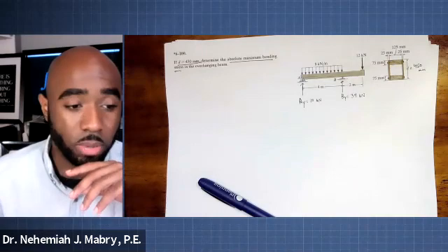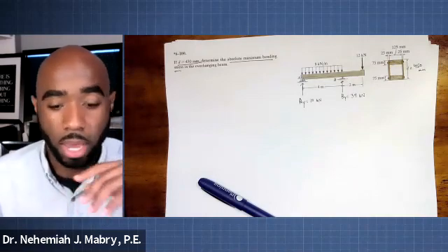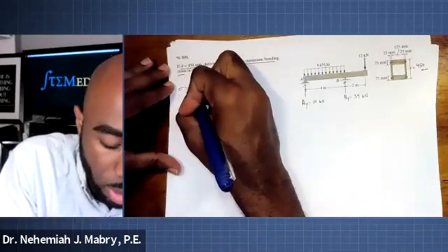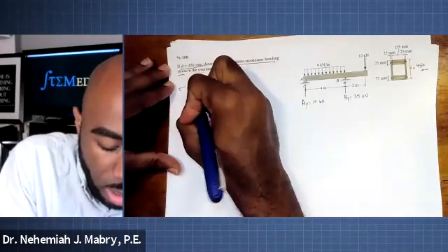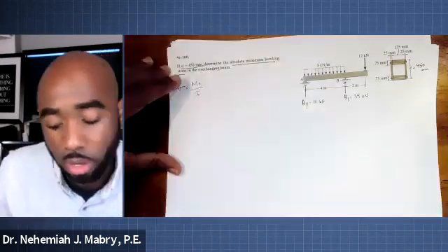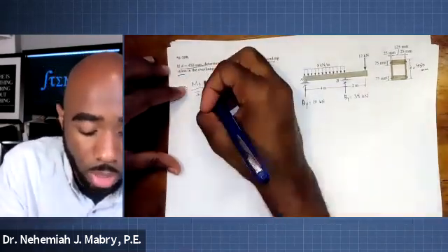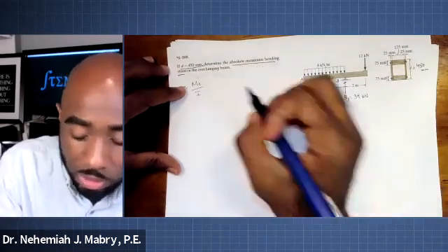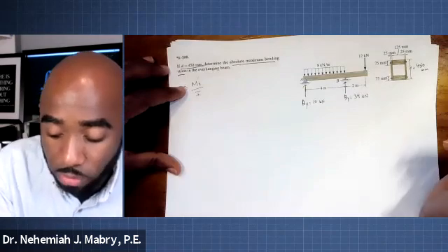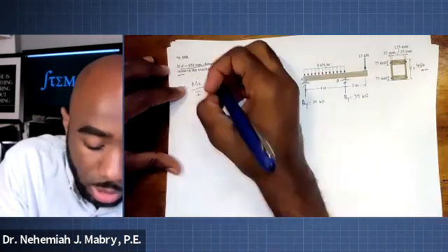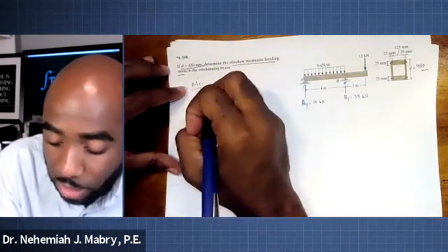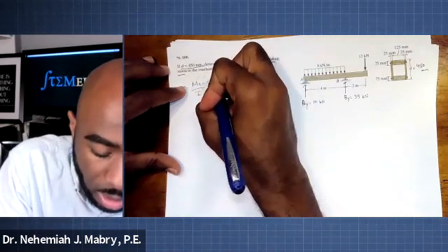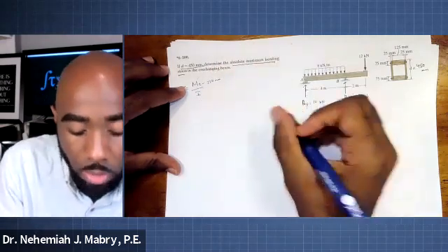So what we need to do next, one of the things we can go ahead and knock out, is find the moment of inertia, because we know that ultimately we're going to be using this equation right here. We're going to find M from doing our shear moment diagrams. We can know that just from looking at this, seeing it is symmetric, right? So what would C be? Well, the height is 450, right? So C, the distance from the neutral axis, is just half of that, 225 millimeters, right? We'll come back to M.